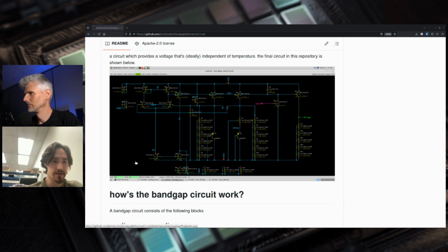And for anyone who might be wondering why I use these dummies in the layout, you imagine you have your circuit with no dummy, and then just look around the edges, right? Because you're not taking up the entire space. And if you were to imagine some deposition or some etching, then right at the edge, there's a change between no circuit and then some circuit. And that circuit is your circuit. And that change on the silicon at that edge, I could wave my hands and say there's a discontinuity there. Whereas in the middle, picture in the middle of your circuit, it's been totally processed, and maybe you have multiple transistors next to each other. And so the point is, why use a dummy? You put a dummy at that maybe transition boundary between no circuit and your circuit.